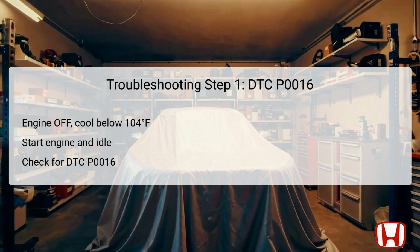The first step in troubleshooting DTC P0016 involves ensuring the vehicle is in the off (lock) mode and allowing the engine to cool below 104 degrees Fahrenheit, 40 degrees Celsius. This is crucial to prevent thermal interference that could affect sensor readings. After the engine has cooled, start it and allow the vehicle to idle without a load, such as in park or neutral (N).